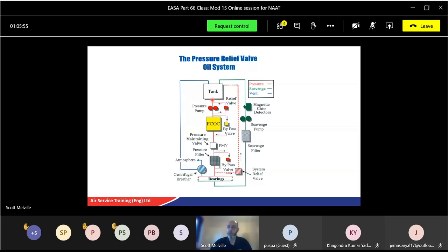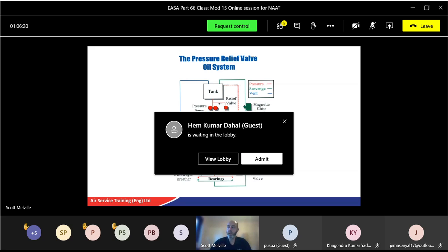So we've got a few more relief valves. Then we've got the fuel cooled oil cooler. So the fuel will be coming in, going through the matrix, oil will be going around the matrix, so the fuel is keeping the oil cool. And as the warm oil gets warmer, that helps warm the fuel up. And again, there will be a bypass valve there for the oil. So if the oil gets too thick, too cold, at least it can bypass the cooler initially to help move on to the actual bearings.